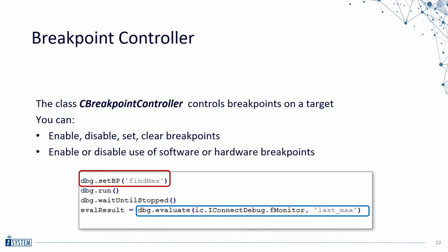As the name implies, the breakpoint controller controls breakpoints on the target. Breakpoints could be enabled, disabled, set, cleared. There is possibility to use hardware or software breakpoints. The sample code presents the simple use of setting a breakpoint at the beginning of the function findMax.